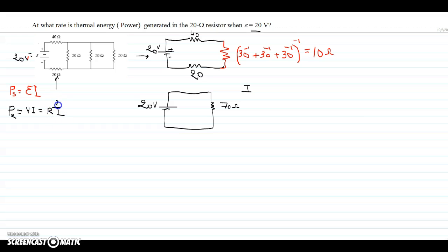Therefore, the best way to evaluate the power anywhere, 20, 30, is to find the current, because current squared times resistance is the power. Another way, if you have the voltage across the resistor, is V squared over R. So we have all choices. The question is, what is the power across this resistor?